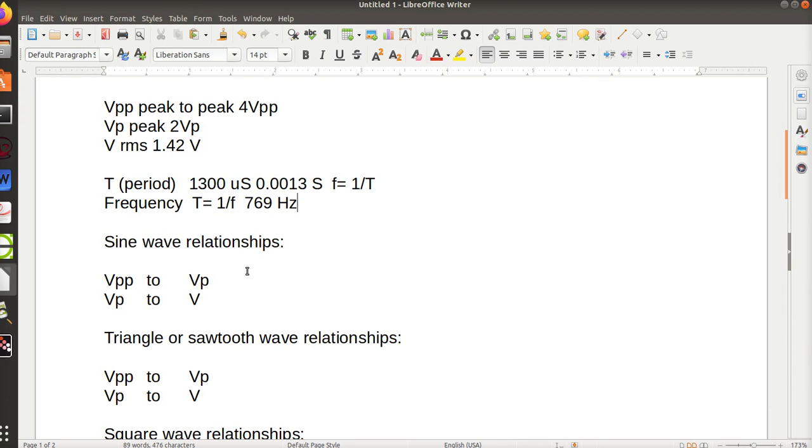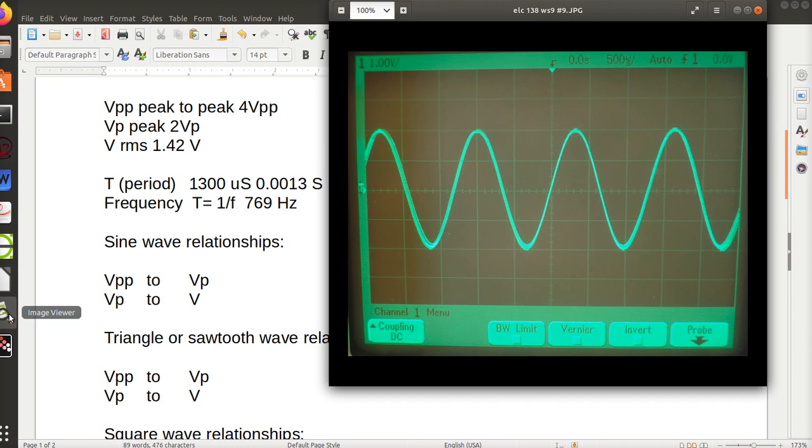Okay, so all the information is there. That's the whole point of the video. If I know the volts per division, I know the seconds per division, and I see a waveform, I can come up with its voltage and I can come up with its frequency all day long. Any oscilloscope. There are more options and settings on oscilloscopes, but for measuring just your basic waveform, this is the fundamentals.